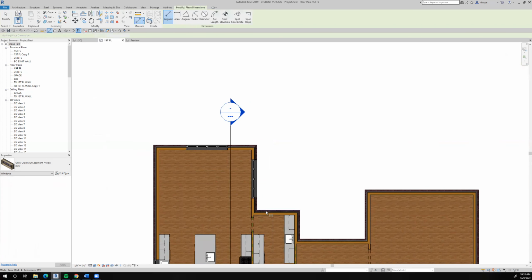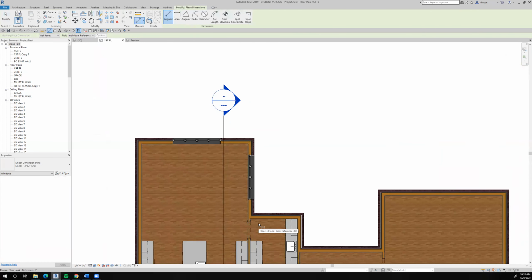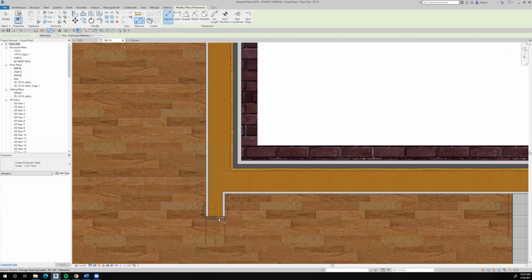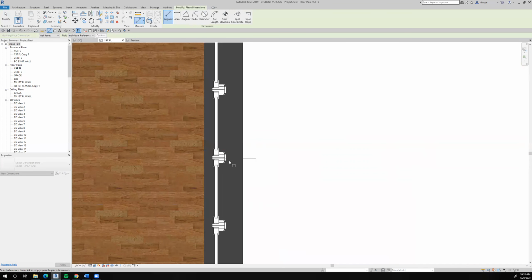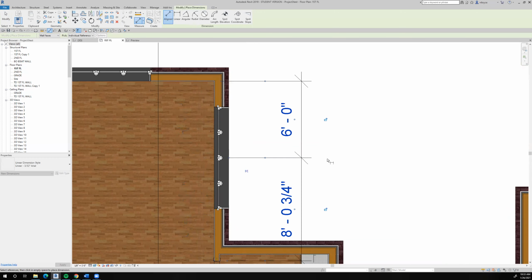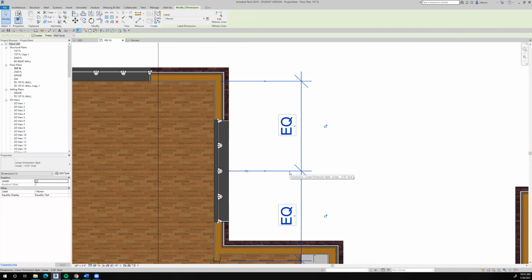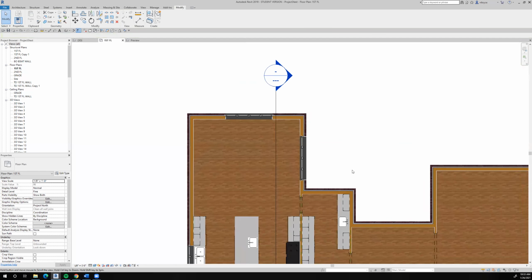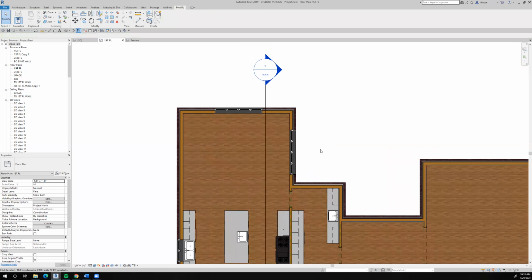And again, how should that be centered? I'll center it from here to here to there and say equal. Okay. Escape, escape, click on that, hit delete, and then hit the enter key. That will accept the notice from Revit that I want to change that. Now I might change the location of that once I put the table in, because it'd be nice if that were centered right on the table. But for now, we'll leave it alone.